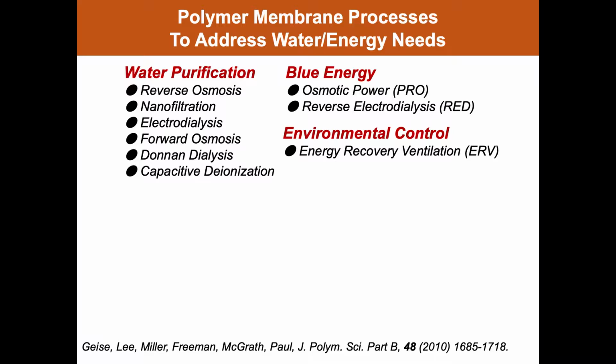What's being done now in more and more building ventilation systems, and in fact in some home systems, is to take the exhaust air, which is cool and low humidity, and contact it across a membrane that's very permeable to water with the air that's coming into the building from outside, and to use that to draw some of the water out of the hot air that's going to go to the air conditioning system. That lowers the demand for having to condense water in the system, which is the energy hog in air conditioning. It's really the condensation.